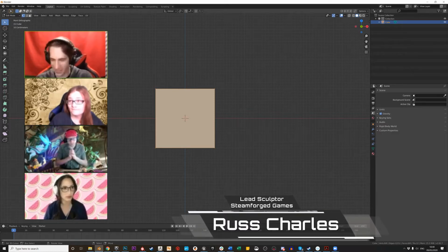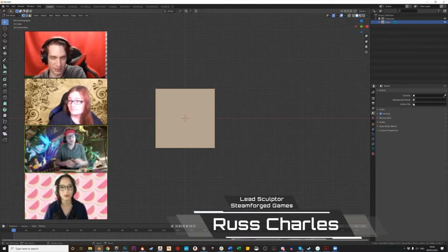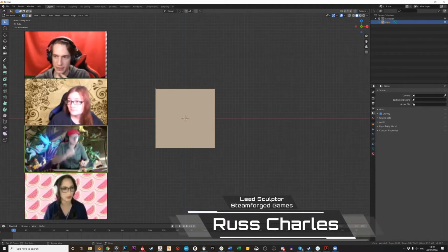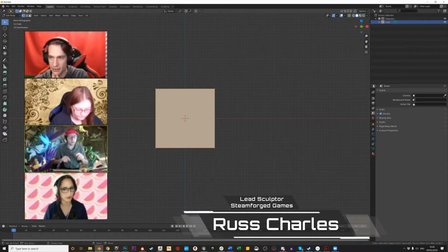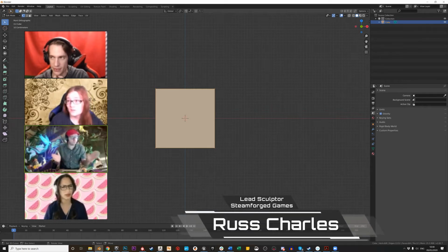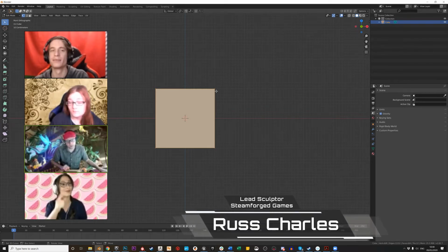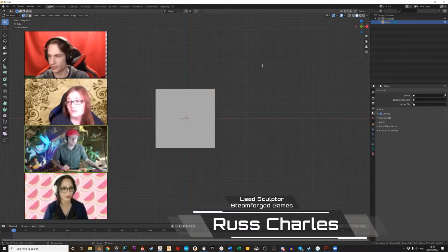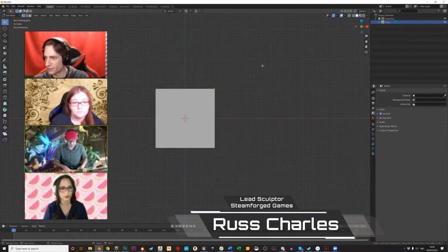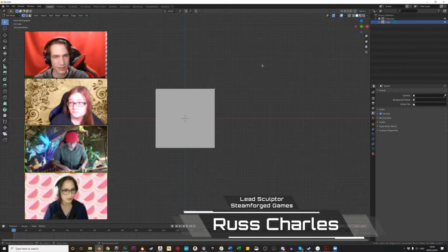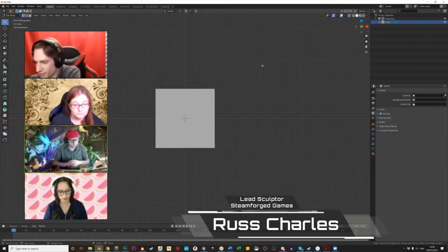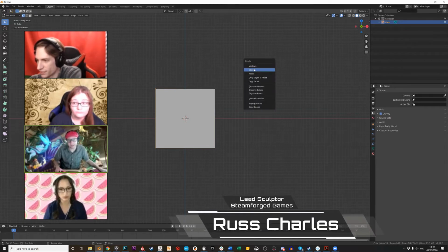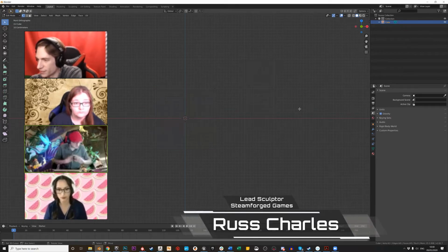To make our sword, what we're actually going to do is delete all but one of our vertices, and we're going to basically dot to dot draw it, use a mirror modifier to create the other half of it and bring the blade together. So what I'm going to do is select one vertex, and then use Control I, or Command I believe, which inverts my selection, press my delete key and delete all my vertices. So that's the first thing I'm going to do.